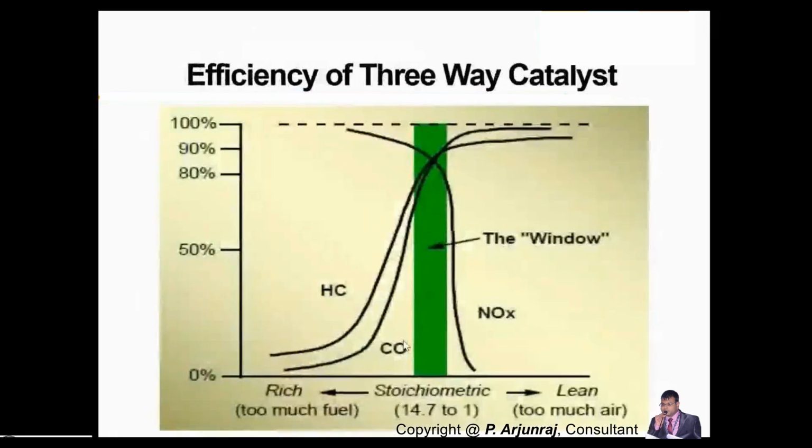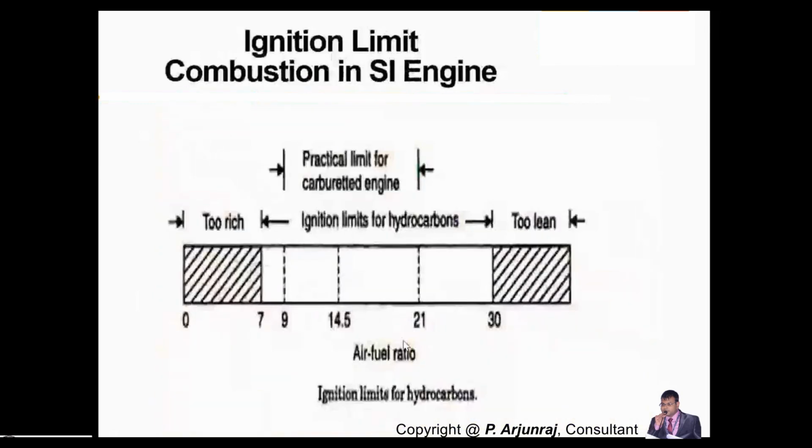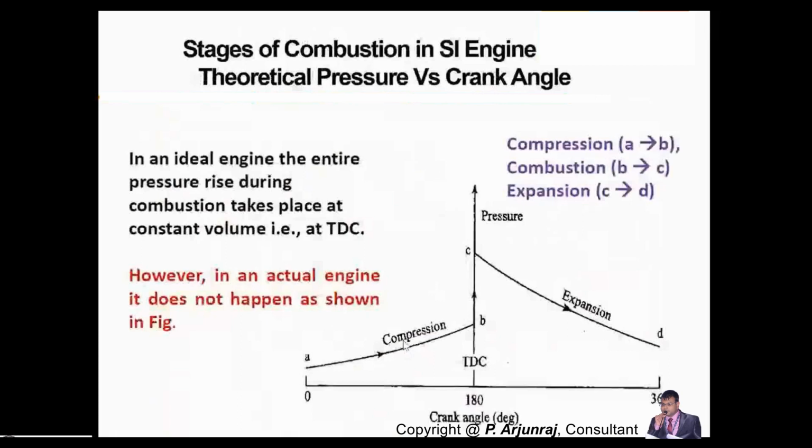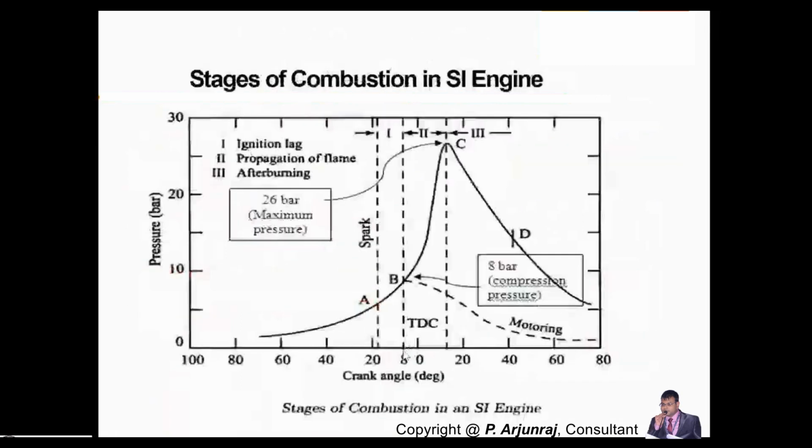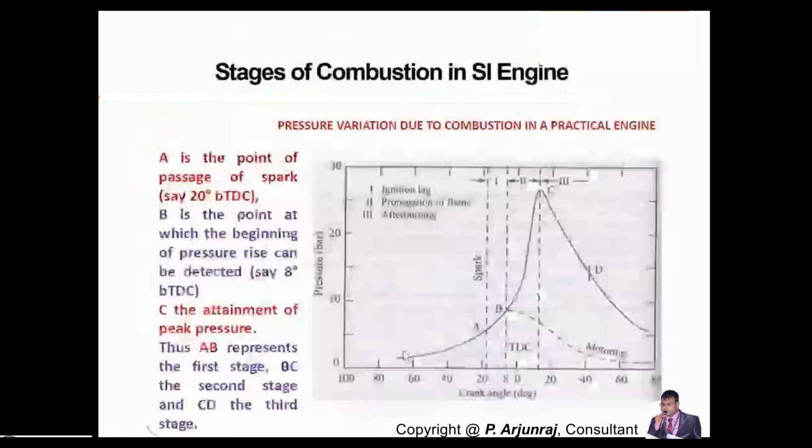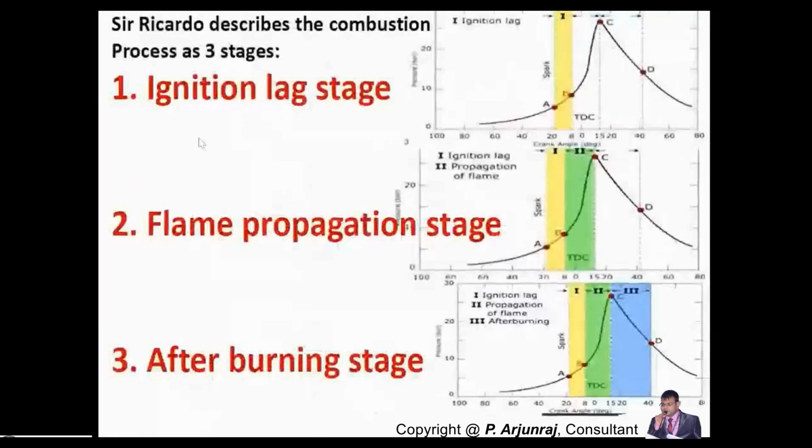Air fuel ratio also affects your catalytic converter efficiency. We have seen the actual combustion stages in SI engine, the theoretical one and the practical one. We have three stages: ignition lag stage, the flame propagation stage, and after burning stage in the case of SI engine.